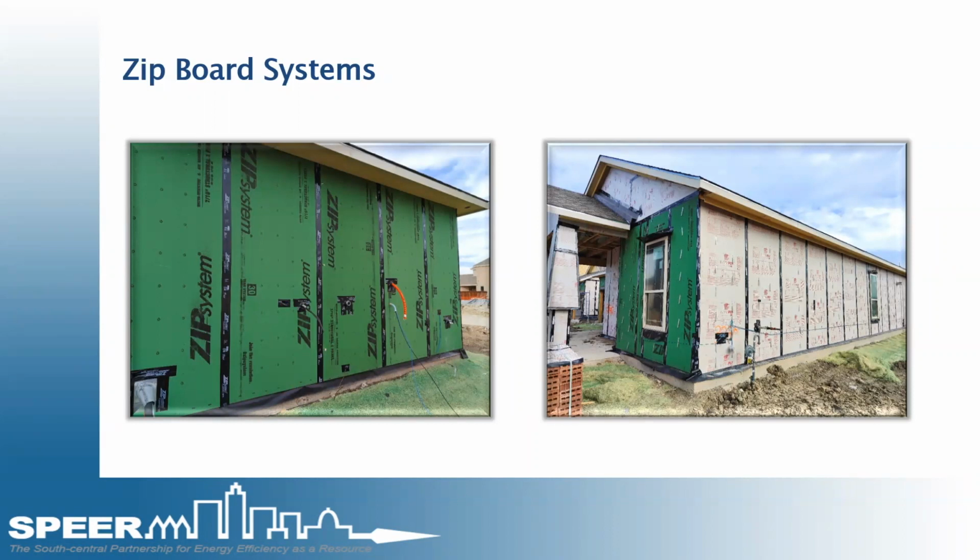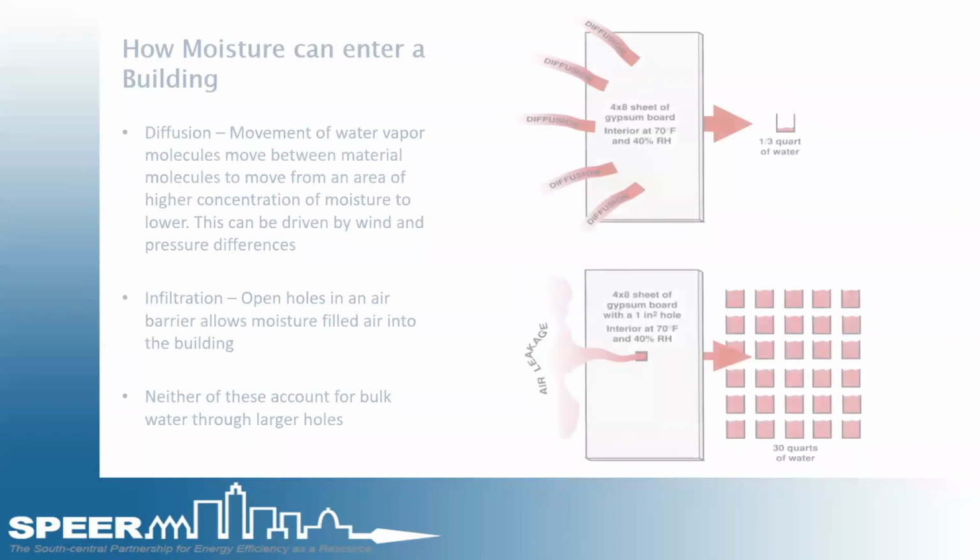At the top of that ZIP board, that tape kind of overlapped a little bit and went down. It creates a good drainage plane, but if that tape doesn't adhere very well, it's an opening to the house itself. They didn't use it running down the lengths of the home. They just used it in certain structural areas on the corners of the house. Butting those two dissimilar products needs to be handled correctly for sure, making sure that the ZIP tape is used and that the seams are sealed as best they can.